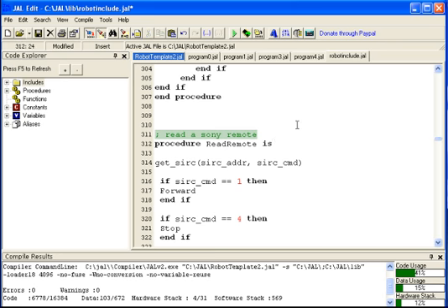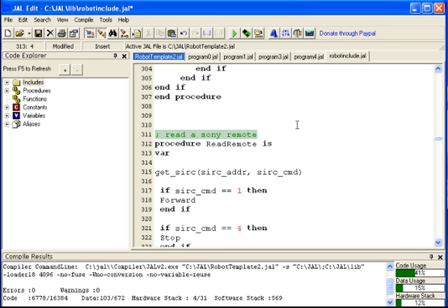So I'm going to reset this up now. I'm going to set up what's called a variable. And you can see I do that by typing in VAR. A variable is a place to store a value or a number. Or in my case, it's just going to be a bit, an on or an off. And I'm going to call that read remote. So there I've got a bit, like a box I'm going to store a number in, and I'm going to make that read remote be true or on or 1.